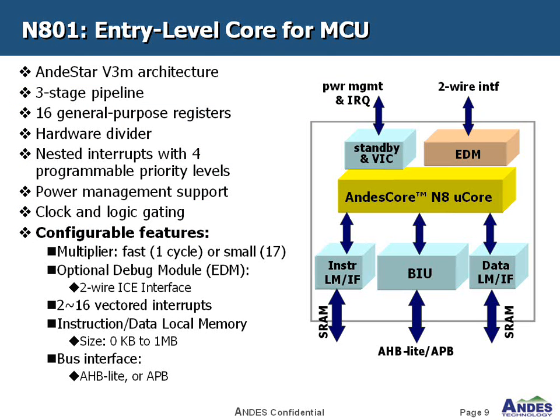Next, I will talk about another entry-level CPU called N8. The N8 is an entry-level core for MCU. N8 is based on N705, but N8 has better performance than N705. The important difference is that N8 has a three-stage pipeline. For the others, N8 is almost the same as N7. N8 has 16 general-purpose registers and an array divider. Interrupt requests can be programmed to 4 levels, and it supports local memory.